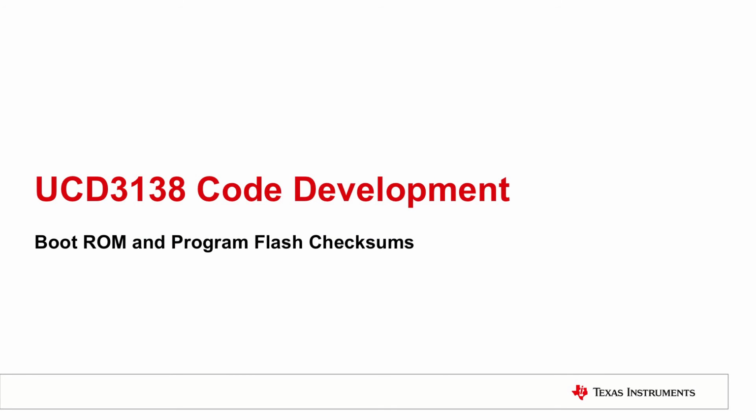I will now give a brief overview of the boot ROM program on the UCD3138 and the placement of checksums when writing to Program Flash. These checksums provide a way for the boot ROM to check the integrity of the Program Flash before allowing the ARM core to execute the code in Program Flash.